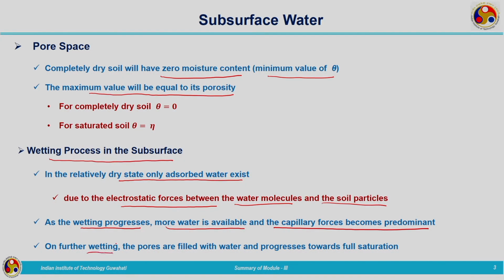After that, with continuous wetting, all the pores will be filled with water and it progresses towards saturation. So, initially it was relatively dry, then electrostatic forces were predominant, then when some more water is added, capillary forces come into action. After that, the wetting process continues, and at that time we will have saturation and gravity force will be predominant.